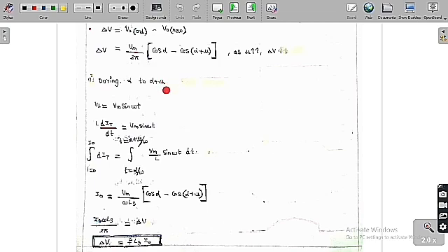During alpha to alpha plus mu, both the thyristor and the freewheeling diode are on. Therefore, if you apply KVL, the supply voltage is equal to the voltage drop across the inductor. So VL is equal to Vm sin omega t, whereas VL is equal to L di/dt, because in that time the current through the inductor is the thyristor current only.